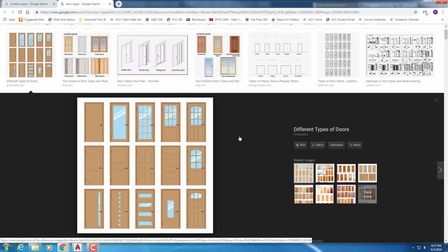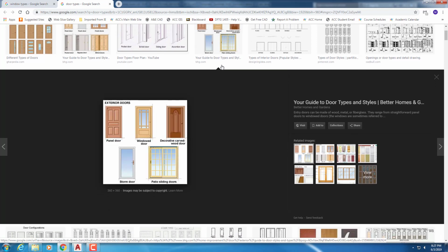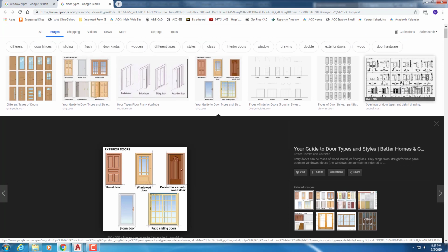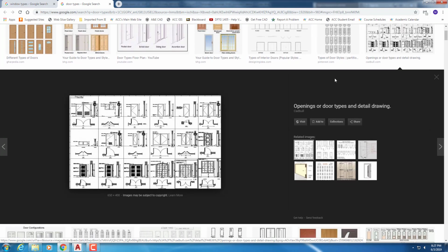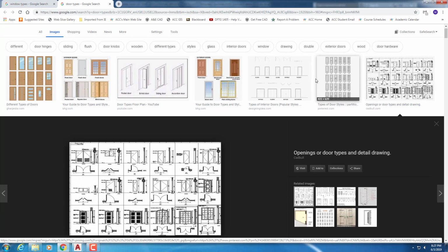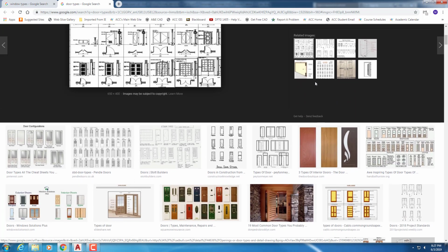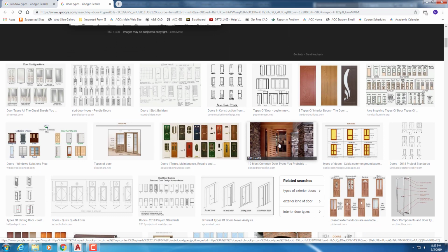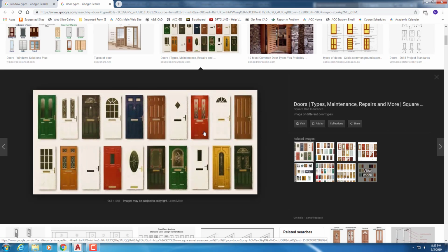And then you've got different types of doors, sometimes solid core, sometimes hollow core. Atrium doors are different than French doors. French doors, typically both of them open in. Atrium door, typically one side is fixed and the other side opens in. So it just kind of depends on the particular door you're looking at the time. You can have a louvered door as well. Different types of front doors.